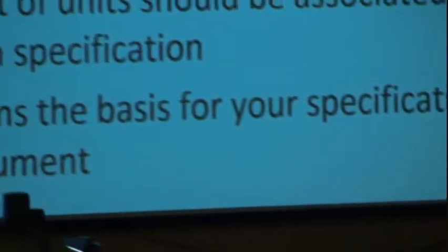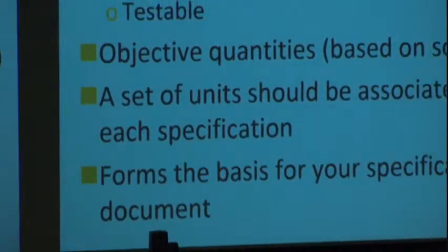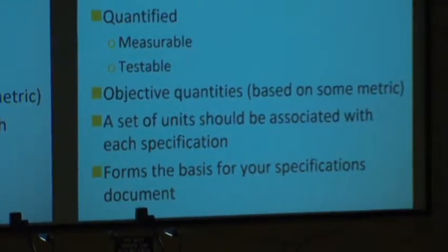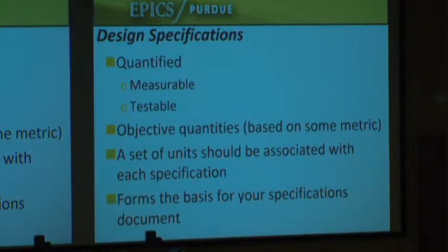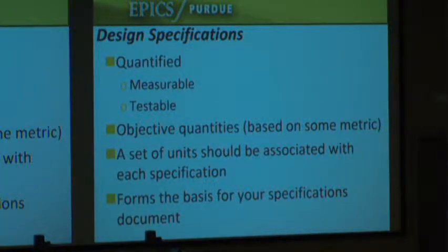As you start to capture all of those needs, understanding that context, understanding how they're going to do that, the end result of the specification phase is having measurable, specific design specs. You should be able to test them, and one of the things to do even at this point is to start to understand, how am I going to know whether or not I've achieved the specification? It might be you actually have to design something into your product to measure something if it's really important. So knowing that ahead of time is really important for your specs.